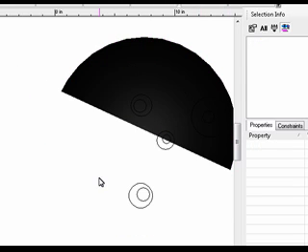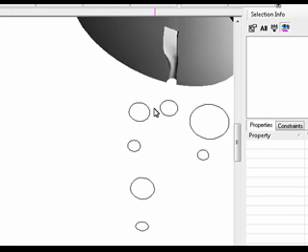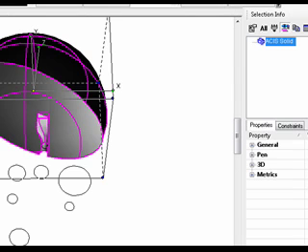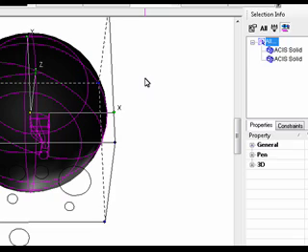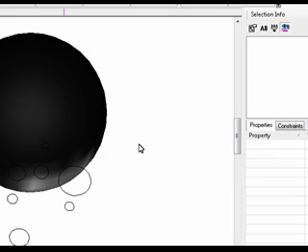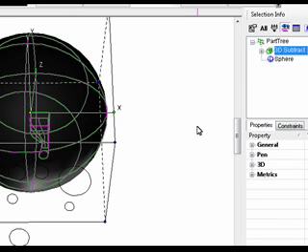Now, what you're going to see is I just blew away my part tree. And that's the important part about keeping your warning dialogues. But if you notice, when I undid, it restored the part tree. Oh, and that's one of the ways the part tree has become much more robust. So even if you blow away the part tree in an operation that normally deletes the part tree, the information is retained and you can back out.